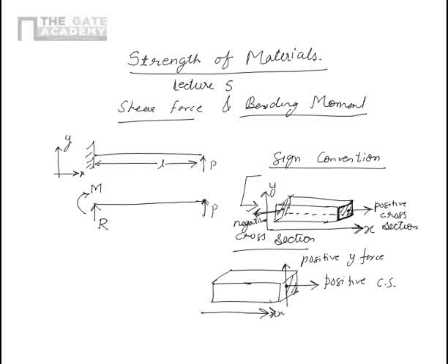So this force acting in positive y direction on the positive cross section is conventionally called positive shear force. Now the same thing is followed here. The shear force which acts in negative direction on the negative plane is called positive shear force.